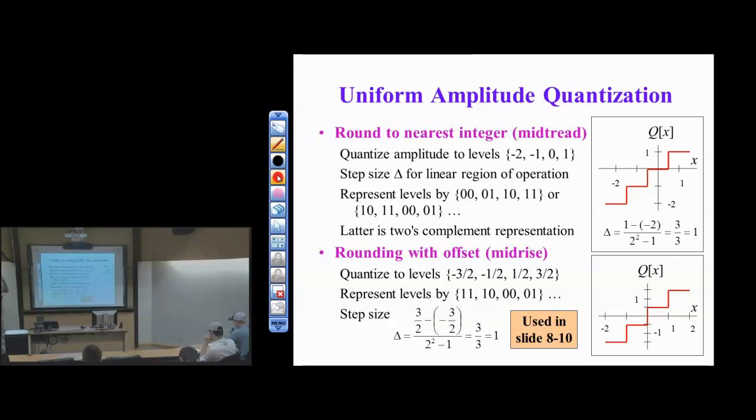Lots of context. All right, so in the case here, when you use uniform quantization, and remember the A to D converter is in our receiver and in many systems coupled with an automatic gain control separate from the A to D converter. So it's another level of sophistication in the system, which can provide some interesting scaling of this quantization effect.